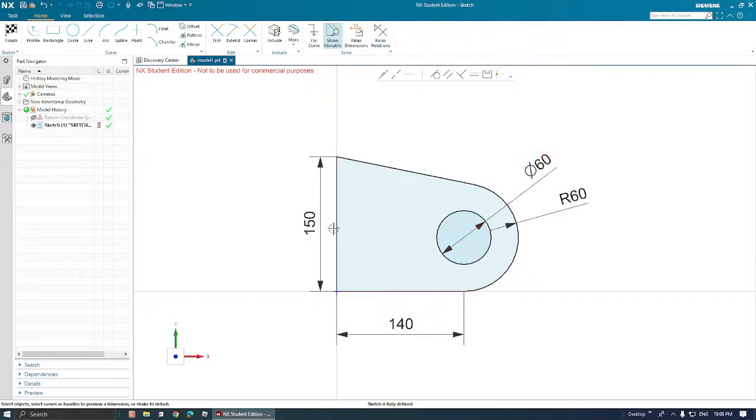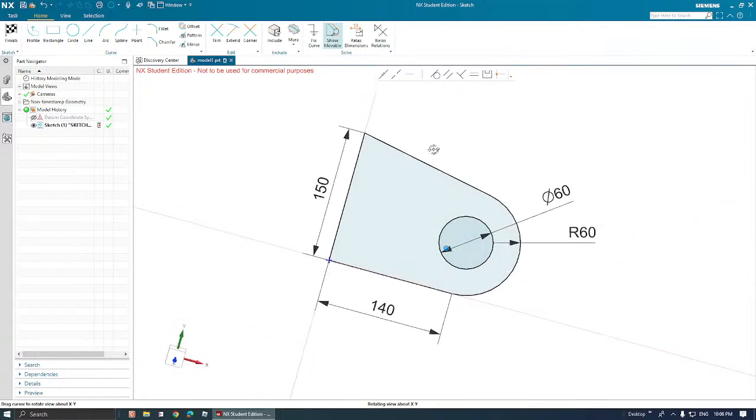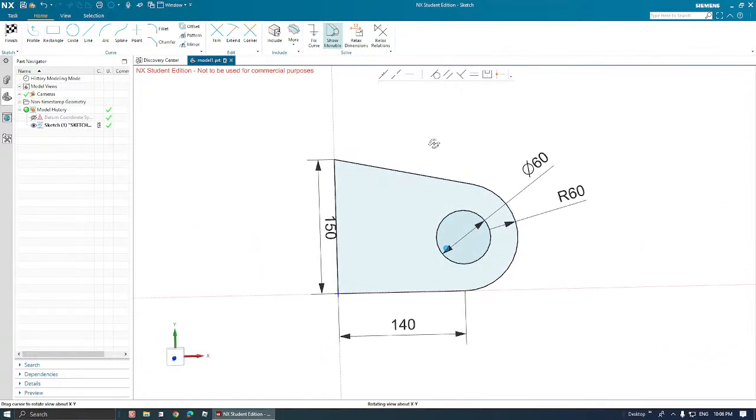For example, we had the geometric constraints and we applied a new geometric constraint. The older geometric constraints were not taken seriously, and the diagram was modified based on the new constraint that I was applying. So it's probably somewhere here that we have the option to determine which one of these is going to be taken more seriously. At least that's how it was in Solid Edge, and because the same company developed both software, I think it's going to be the same way as well.